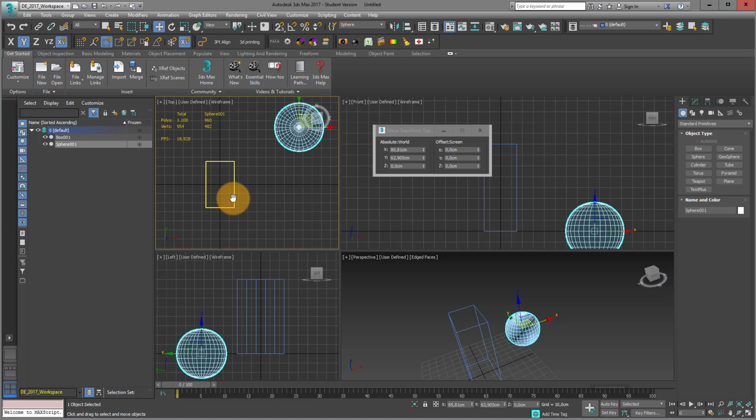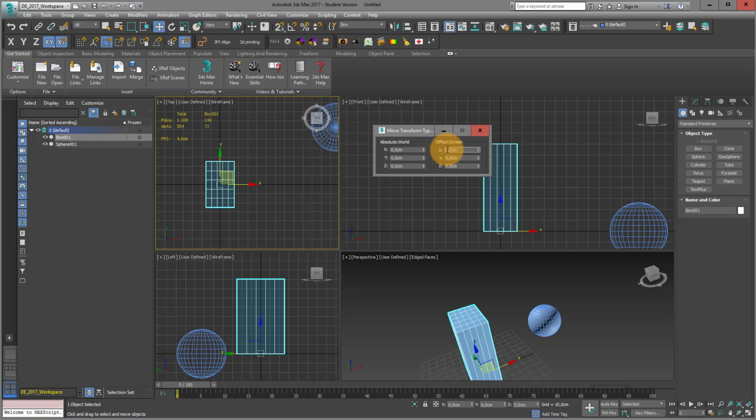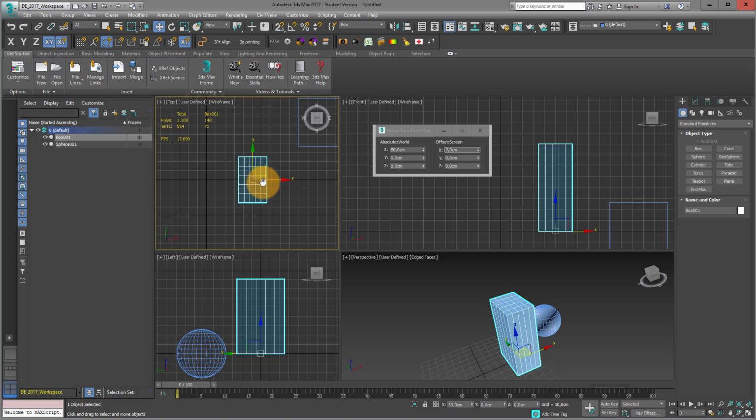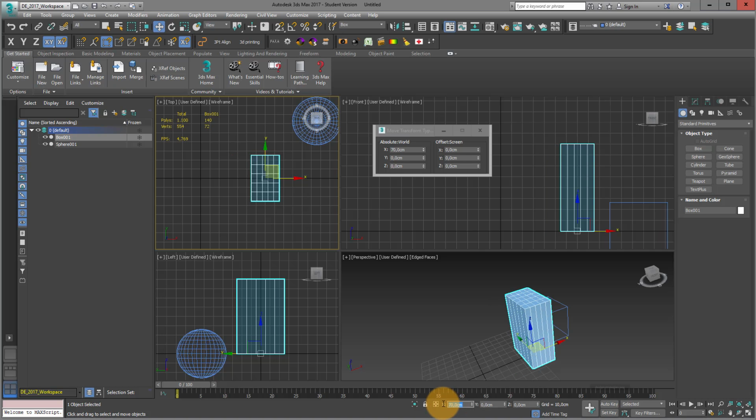to the object. So if I just moved again 40 centimeters in X direction, then after closing my function with the enter key, it's 0 again. And you can just do it with right mouse click. What you can also do is you can just change the number in the lower part of your interface in this area. And now again, I just say I want to move it 60 centimeters, and now it's at this position.